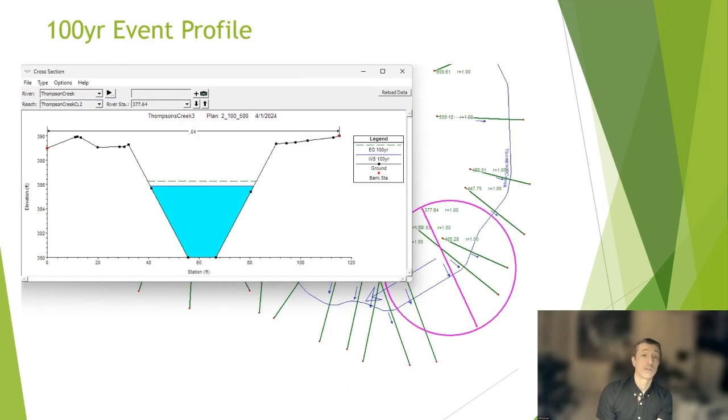The 100-year water surface was used to determine if the proposed bridge height was adequate. The Washington Department of Fish and Wildlife recommends minimum freeboard of 3 feet below a bridge during such an event. And this profile shows that there is a 4-foot elevation difference between the existing road and the proposed creek surface below, so it's within the required specifications.